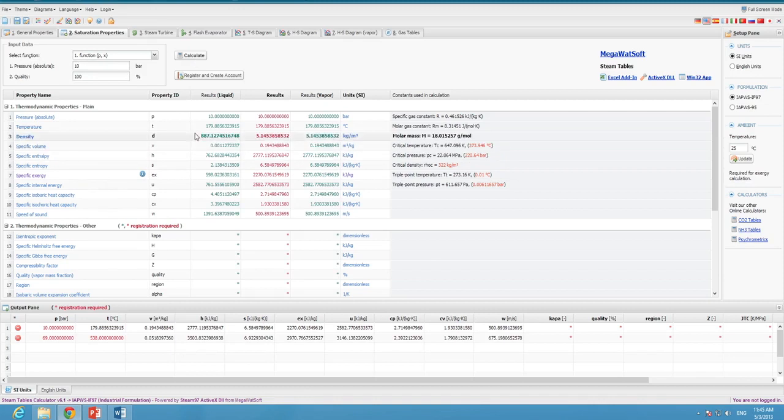And what we want to take back with us is the specific volume at this condition is 0.001 meters cubed per kilogram. And be sure you check those. Oh, I'm sorry. We wanted this. I read the wrong side. That's the saturated liquid results. We want the saturated vapor results. My apologies. I read the wrong column.